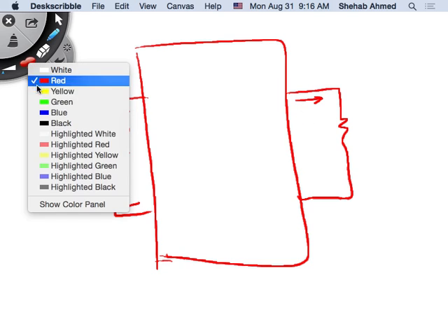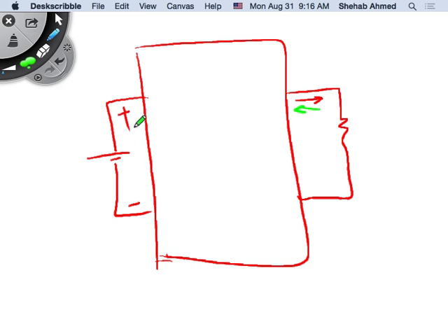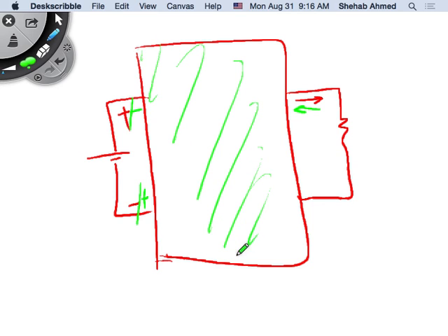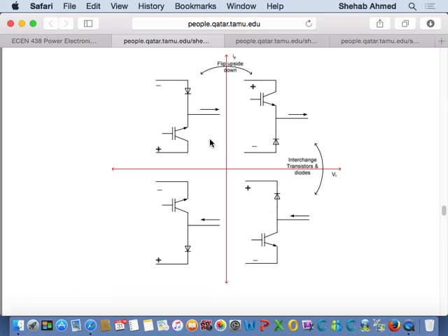So you can do anything: voltages positive, negative, currents positive, negative. You can do anything you want, right? And you have to choose something in here that will make it happen, right? There's something in here that will make it happen. You can cheat from this table, or you can go through the logic that we went through: okay, current can flow, current will not flow, MOSFET's positive, MOSFET's negative. You can look at the switching characteristics of the diode and the MOSFET. We'll go through an example of that as well.